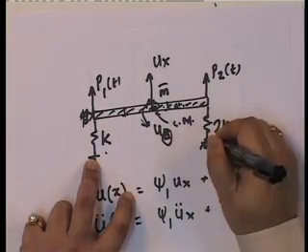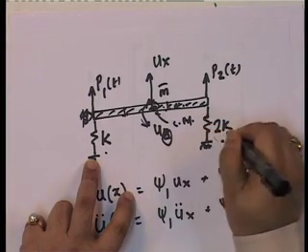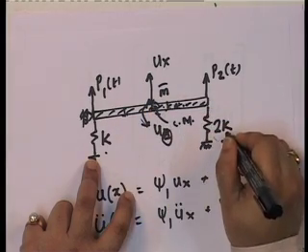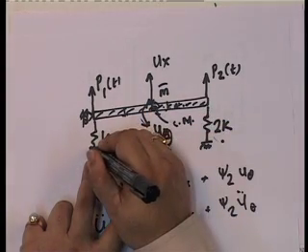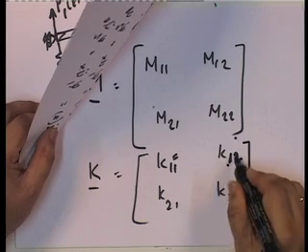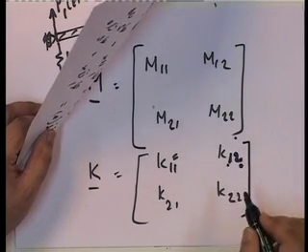So, see this one is coming this way, this one is going this way, this is kL by 2, sorry kL, and this is kL by 2. So, what is the net force here? kL minus kL by 2. So, that is the force, that is kL by 2. So, you see it is a force corresponding to degree 1 due to a unit displacement corresponding to degree 2.